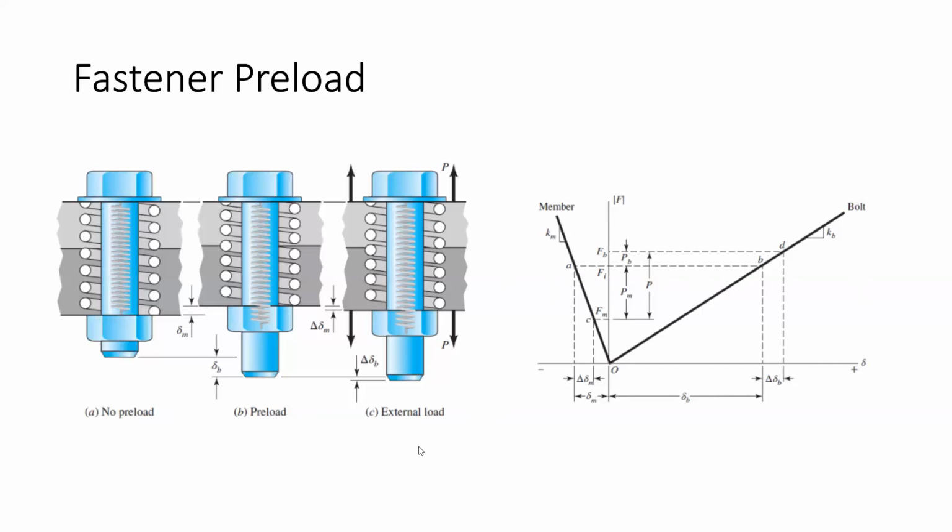So when you pull on this bolt, something that you really care about is obviously how stiff is the system. If I were to attach a load to this darker gray plate and pull on it, how stiff is the system going to be? And it turns out the answer to that is it's a combination of both the stiffness of the bolt and the material. But the super unintuitive thing is that it also depends on your preload. So there's something called joint stiffness that I talked about earlier, and that joint stiffness is actually dependent on the amount that you torque this bolt down. So larger torques and axial preloads on your system aren't just good from the point of holding two plates together to react to shear load. It's also good because it can increase the stiffness of your system.